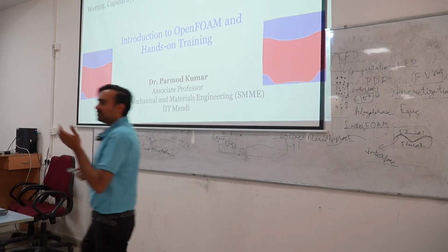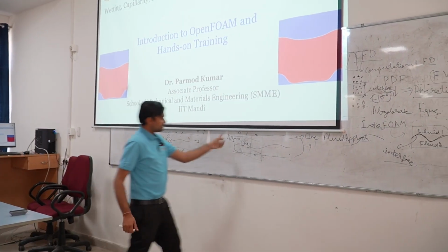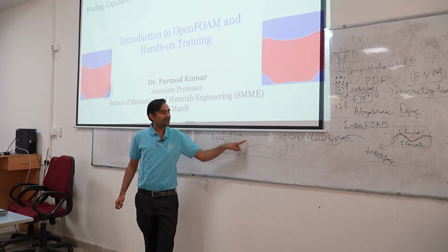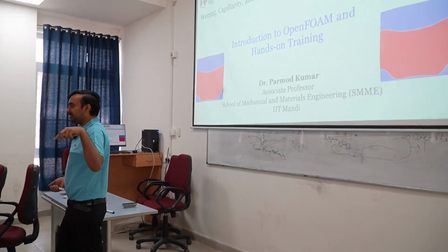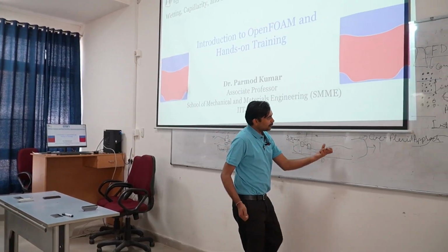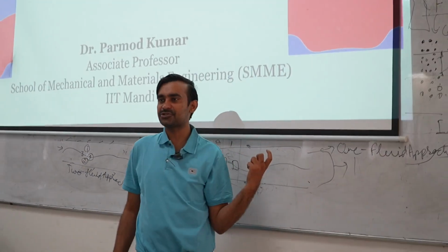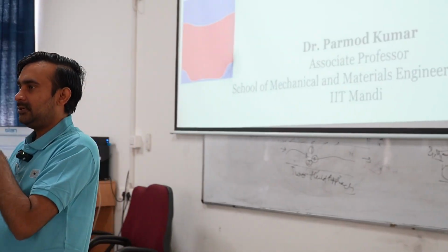When we are using the one fluid approach, we still have an interface, so our continuity and momentum equations will remain the same, but in addition, in the momentum equation, we have to add some additional force term which can account for the different forces acting at the interface.